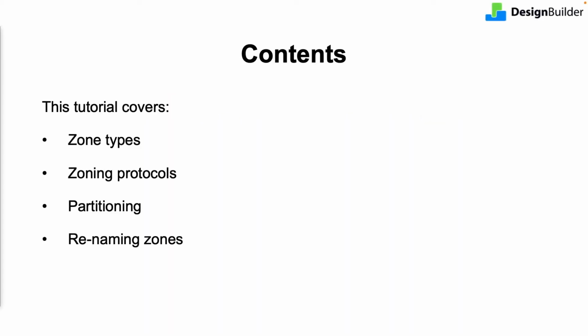Hello! In this tutorial, I'll show you how to create zones within building blocks. During the tutorial, I'll explain the available zone types and zoning protocols, and then show you how to create zones using partitions, and finally how to rename the new zones the partitions create.